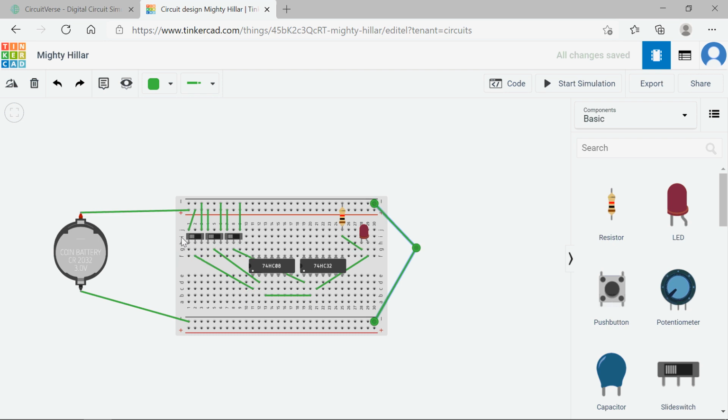So with the switch on the left, it is connecting the positive end of the battery as the input to my logic gate. Now, I think I forgot, yeah, I did not power these gates yet. So to power them, see that's power and that's ground. So this is the power line here. I'm going to connect VCC of each of those two gates up here to 5 volts.